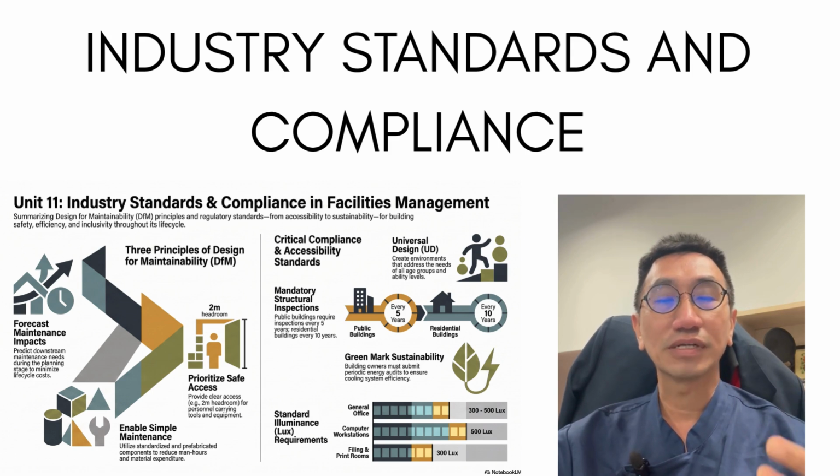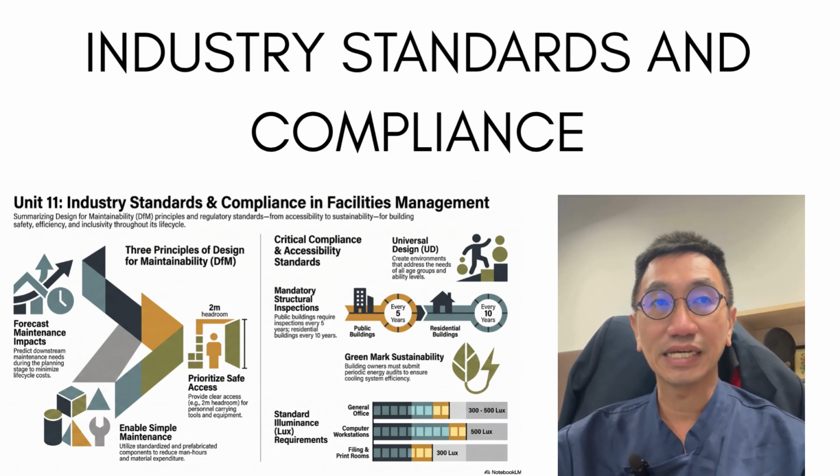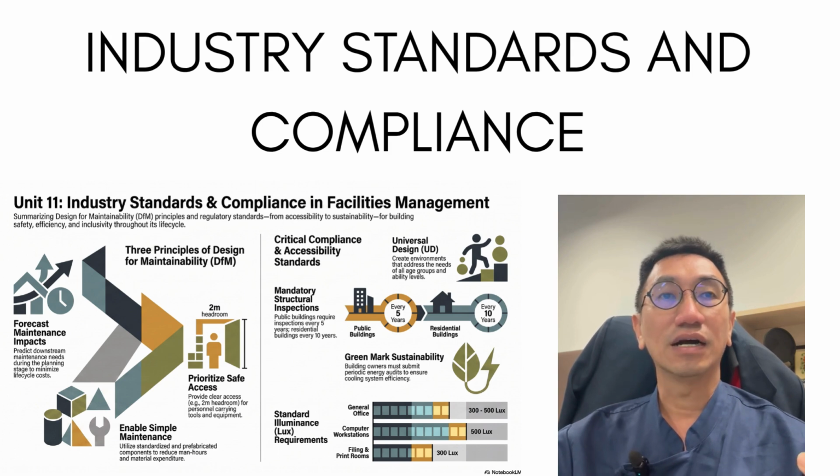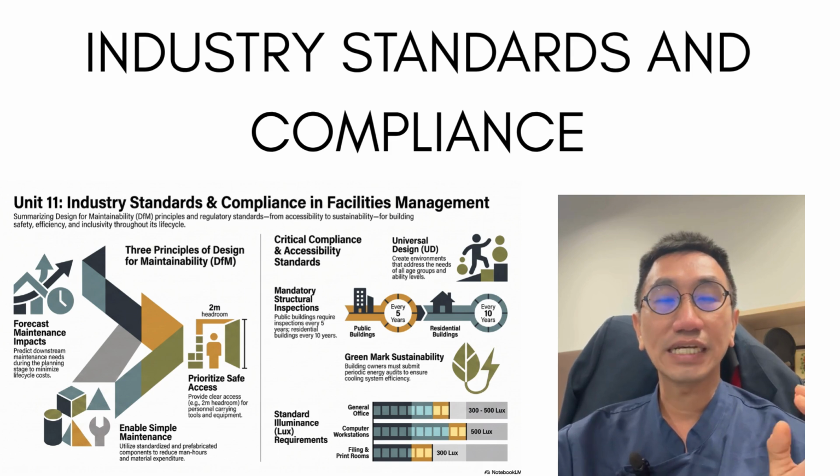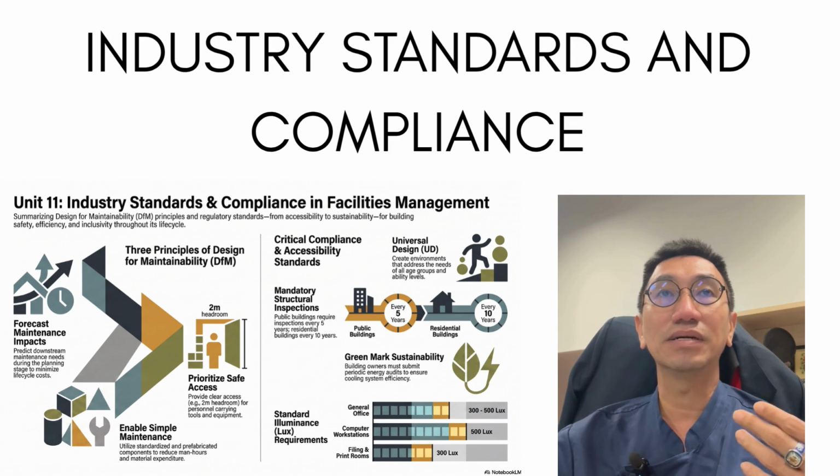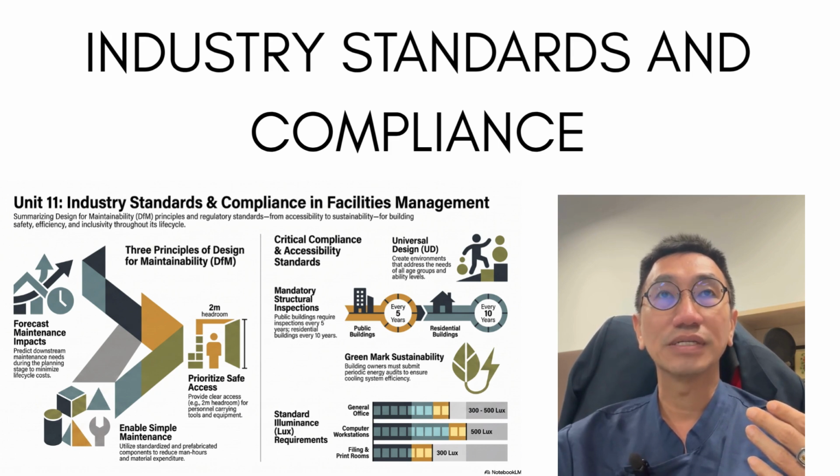Three other important Singapore standards that we always learn are SS530, the code of practice for energy efficiency; SS553, more related to air conditioning, mechanical ventilation, and indoor air quality; and SS554, mainly on the quality of air. These are essential for facilities managers, and we need to ensure that operations are compliant, safe, and sustainable.